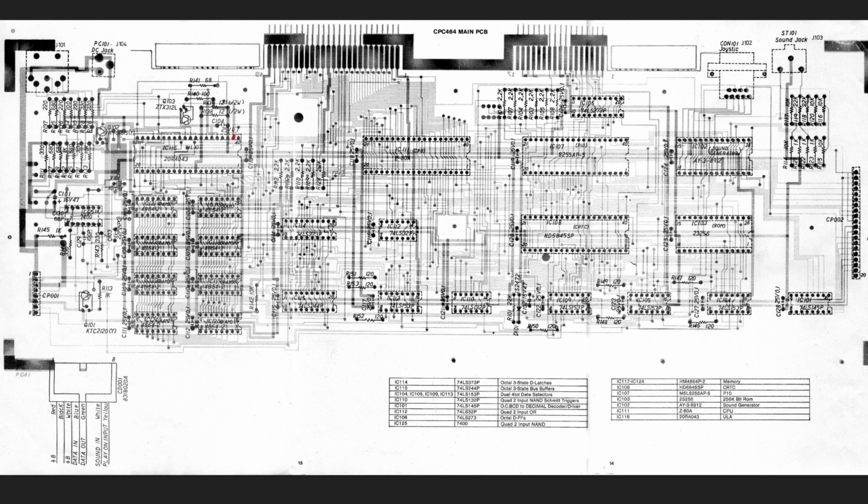Maybe it was a routing issue since the signal needs to move away from the CPU a bit and then travel back to the CPU? I'm not really sure, but certainly the second revision makes a lot more sense. And so there you have it. The moral of all of this is that finding a good transistor equivalent isn't trivial, and it's worth taking the time to understand how exactly it's going to be used. Obviously, doing this with every transistor is exhausting, but once someone does it, hopefully it goes in the bill of materials for the project and everybody can safely use that.